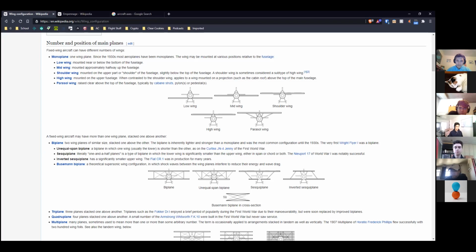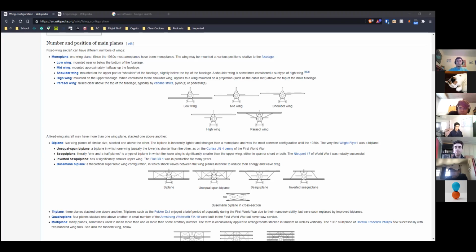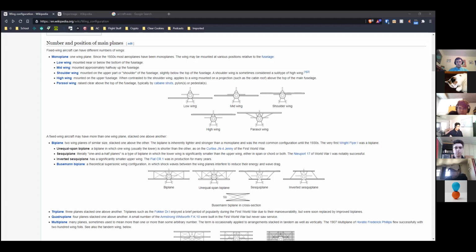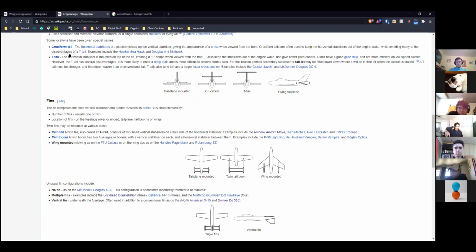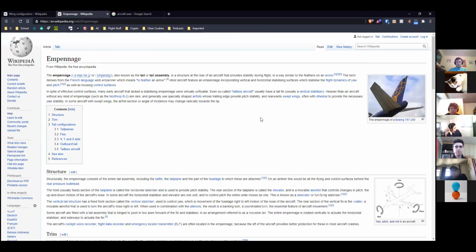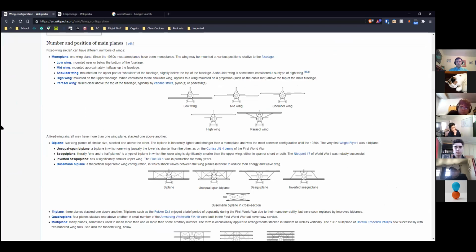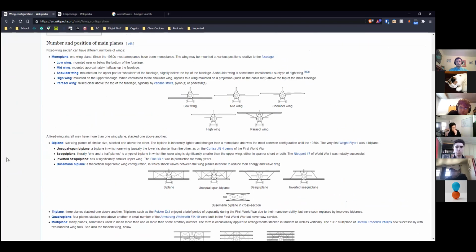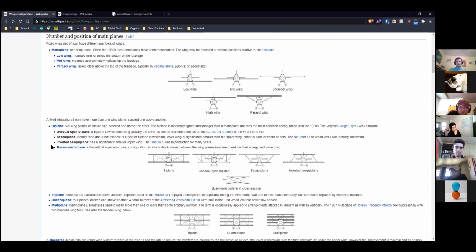Where you put your wing will determine a lot of how your plane flies, and it'll also eventually impact how you design your tail, because the wing and the tail, I mean, as a quick aside, the entire point of having a tail on your plane is that if you only had a wing and a fuselage, it would continuously nose up forever, no matter how fast you're going, unless, as we'll see farther down, you specifically design your wing in such a way that it acts as a tail also, but a normal plane, air quotes, doesn't do that.